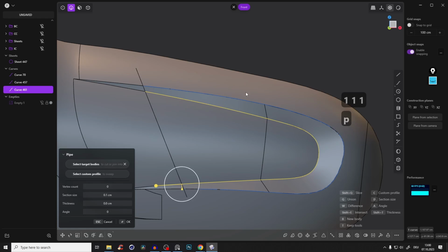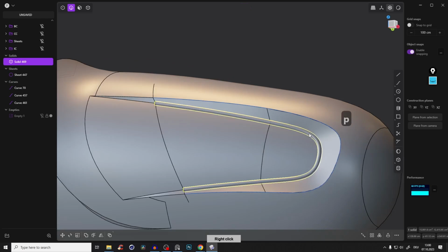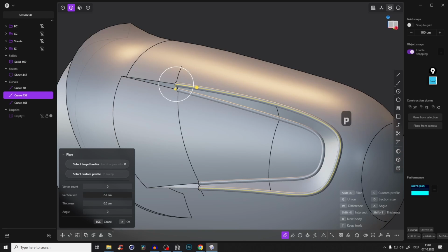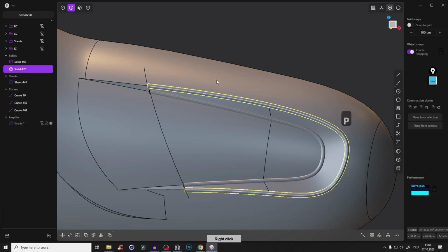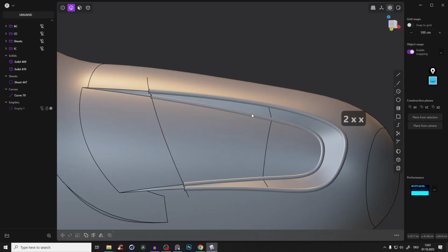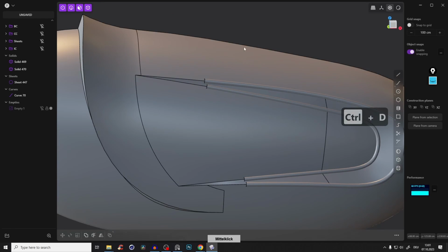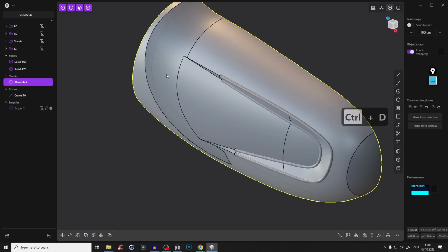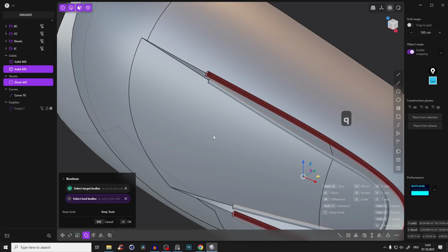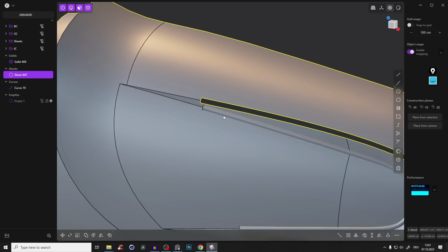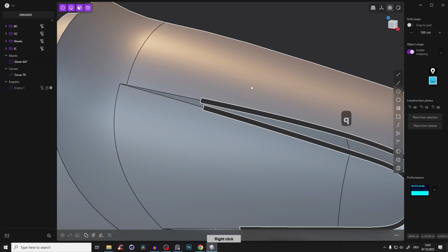Okay. And select this edge and give it a section size. It has to be something like what you want the fillet size to be. So give it a little bit here. Something like that. That looks fine. For the tutorial, it's perfect. And that looks amazing. Now let's go back to our surface. Shift D, delete redundant topology to get rid of this extra edge. Now select the surface and shift click this new cylinder or pipe, right click and Q and delete it. And again, select that and that, press Q, delete it.